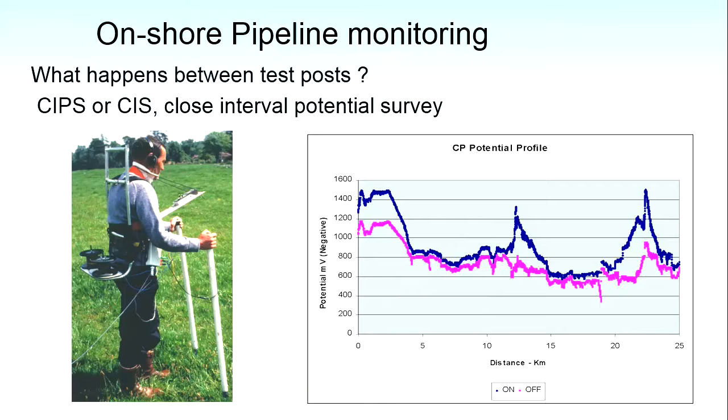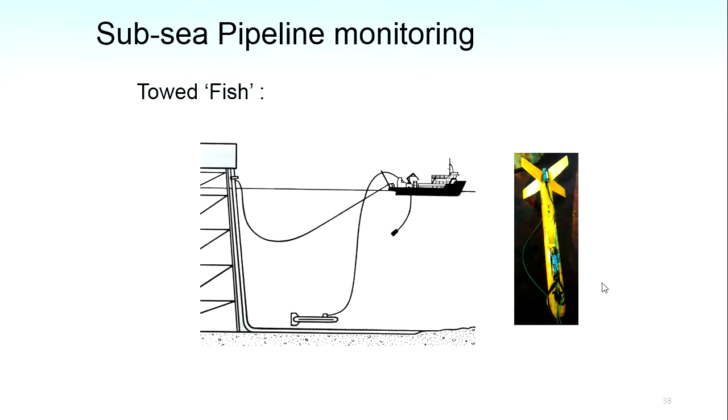Another way of doing it are these ROVs, or remote operating vehicles. These are unmanned mini subs, really, mini submarines, and quite often have quite a lot of kit on them. This one's actually looking at a seabed line with anode bracelets on it. Okay, so at intervals there's a bracelet of probably aluminium zinc alloy or something like that.